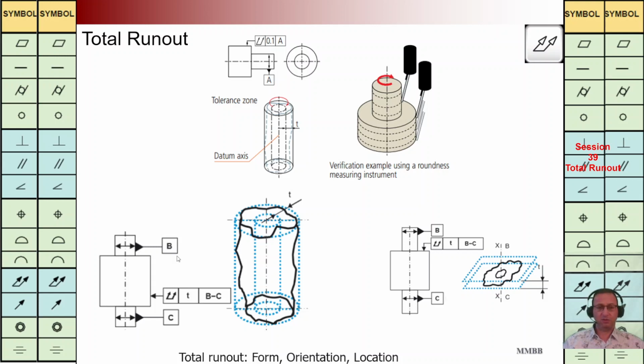And also at the bottom left, we are going to have this total runout Tz is T back to BC axis. We are going to have two coaxial cylinders that are highlighted by blue dot points, and that profile should be in that Tz whenever we are going to rotate the component, and the dial indicator is going to move on this surface.